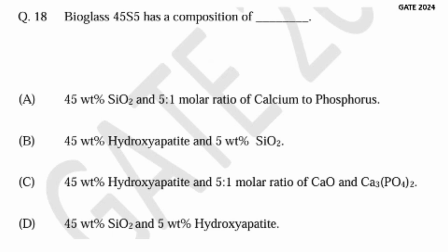The standard composition of Bioglass 45S5 is 45 weight percentage of SiO2, that means silicon dioxide, 24.5 weight percentage of Na2O, that's nothing but sodium oxide, and 24.5 weight percentage of CaO, calcium oxide. Lastly, 6.0 weight percentage of P2O5, that's nothing but phosphorus pentoxide. This composition enables the formation of a bioactive layer of hydroxyapatite when the glass comes into contact with body fluids, which is crucial for bone bonding. So this is the basic concept of Bioglass 45S5.